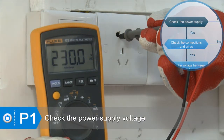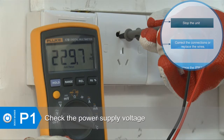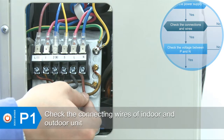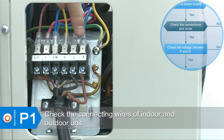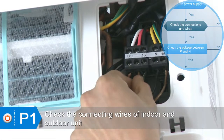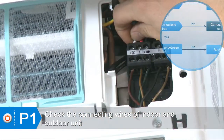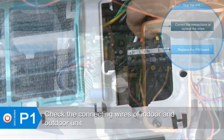Check whether the voltage is normal. If the voltage is abnormal, stop the unit. If the voltage is normal, check whether the power wires of the terminal in the indoor unit and the signal wires are good. If not, correct the connections or replace the wires.